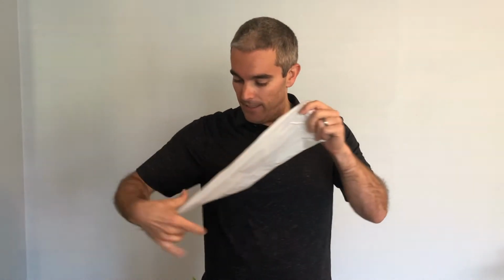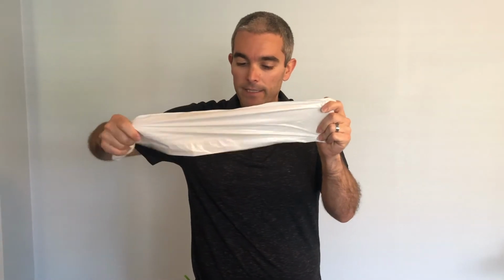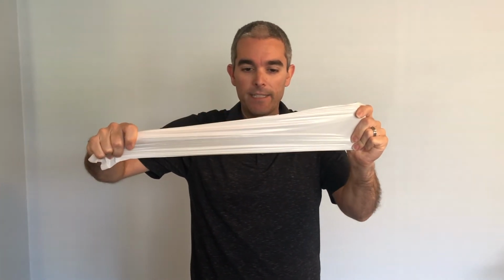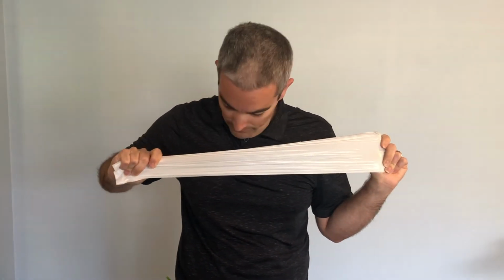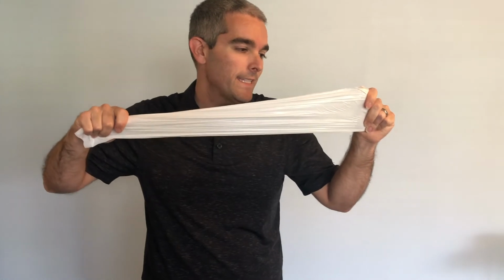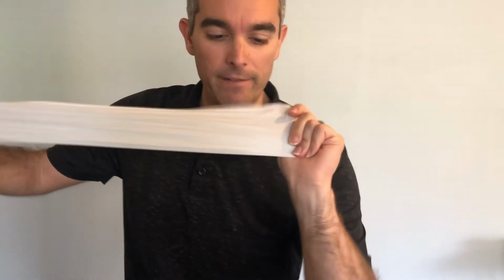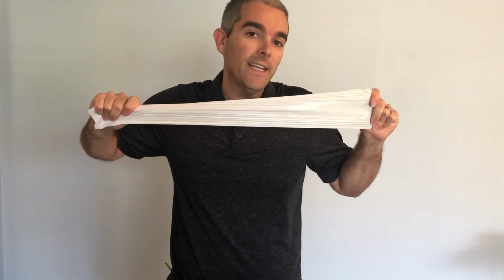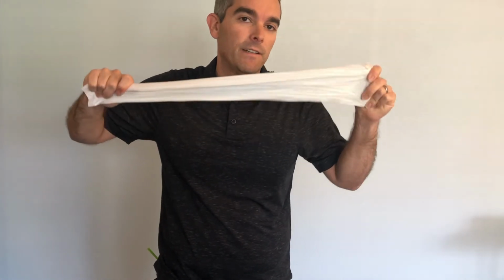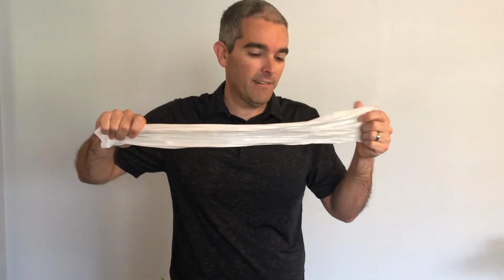The first one is if this whole thing stretches, right? So if I go ahead and pull on this, you'll see you get something like this, and you can see the stretch as we go. If you remember back to mechanics of materials, we did a stress-strain curve for something like steel, and we saw that as we pulled on the steel, it would stretch and stretch and stretch. You might be able to see the plastic stretching. You get some 45-degree angle pieces, kind of like those Lüders bands, where we're starting to experience some sort of shear, if you go back to Tresca's criterion.